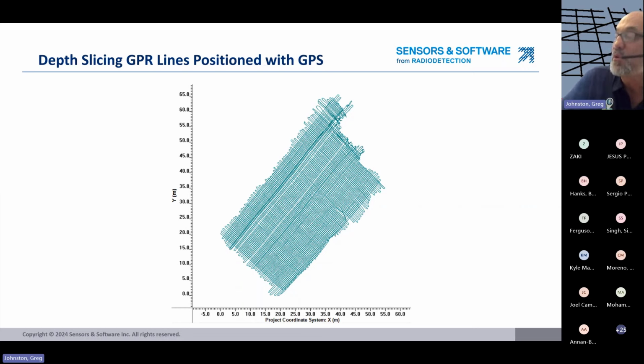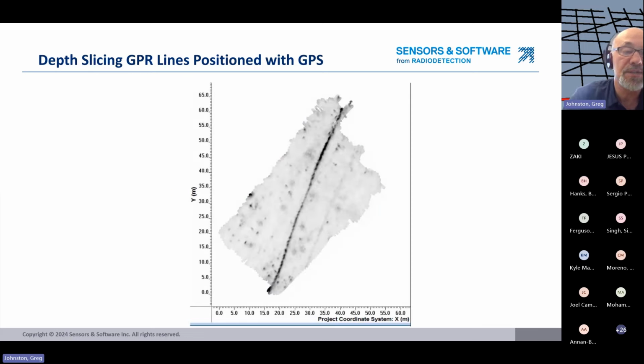So if you look at this example, you can see somebody collected this area in 2 line scans. They collected one line running in one direction, and they just zigzagged back and forth. And if you look at the edges, you can see the curved path as they go around the edge and then come back. So these lines are probably a couple kilometers long in each direction, but we've covered a very large area to do this. Now let's turn these into depth slices. We can use the slice view lines option in Echo Project to turn this into depth slices.